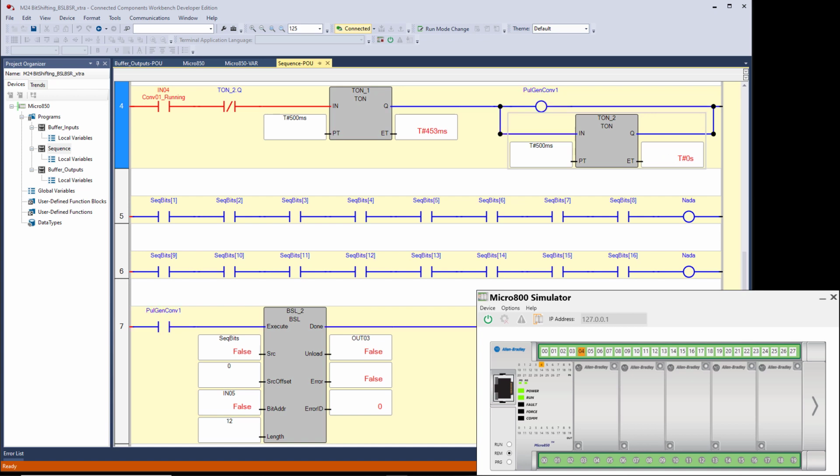to initiate or to control the pulse generator. Now remember, the pulse generator was an encoder type device that had wheels on it, and it ran against the conveyor belt. So whenever the conveyor belt was moving, the wheels were rotating and generating a pulse. And I'm using a 1 second pulse, half a second on, half a second off, because if I run it any faster, then the bits don't update in our little virtual HMI here. So this is where we're going to watch the objects move across the conveyor.